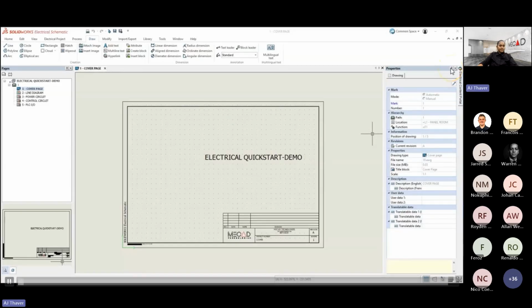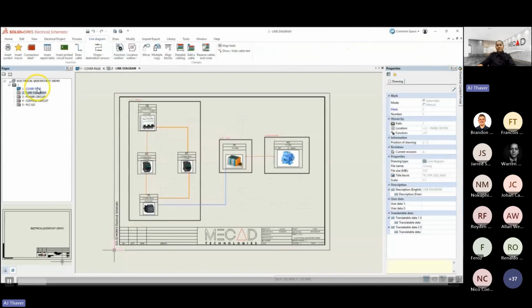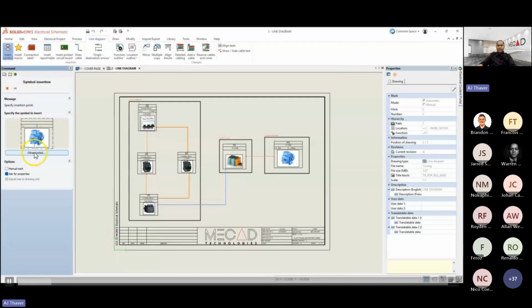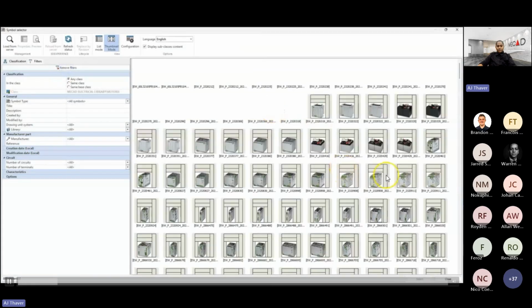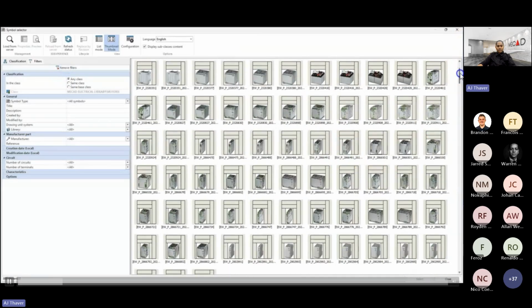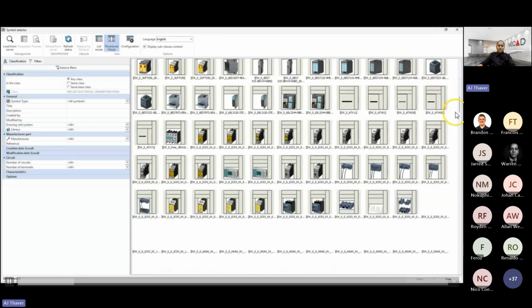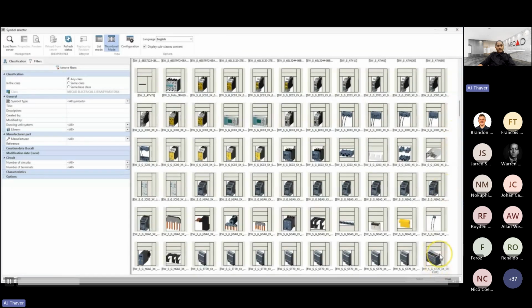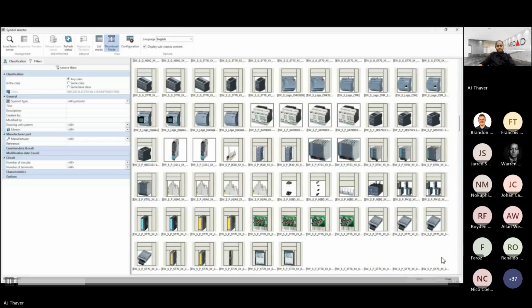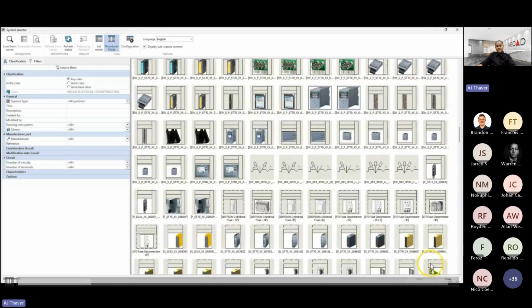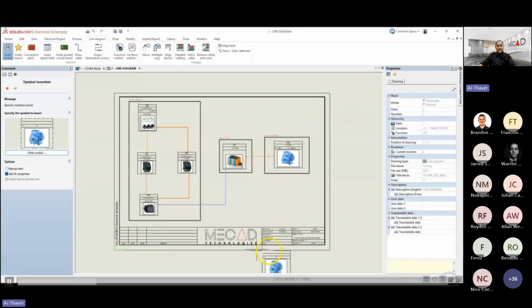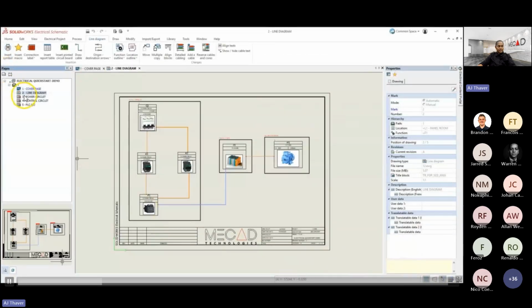When placing components, SOLIDWORKS Electrical is not just dragging and dropping a picture on the page. You're using intelligent electrical elements that already understand their electrical behavior, their connections, and the standards that apply. For example, if you're wiring a starter or a PLC module, the system already knows the correct terminals, the wire connections, and their part references. This means there are fewer errors, less rework in the process, and the schematics are correct as soon as you place them.